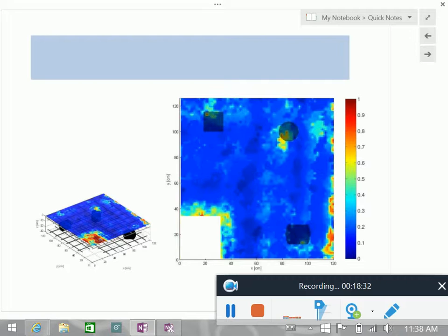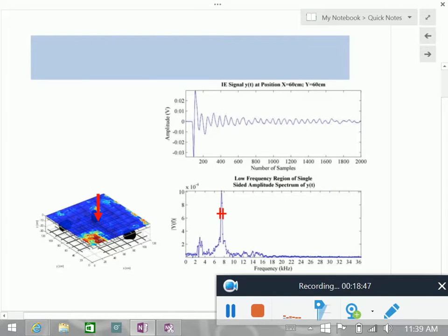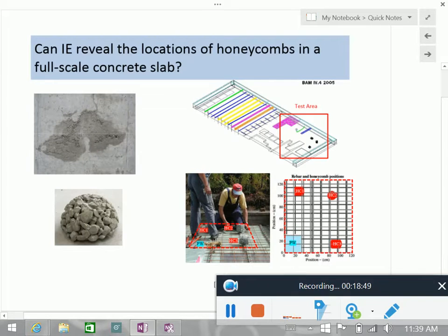So in reality, can you use a hammer to hit the material? We really don't use a hammer in impact echo. Do I have a picture of our impact echo device? No, I can draw it for you. There are different ways. Basically there is a mechanism where you have a small sphere, and let's say there is a magnet that releases it, and then you have an impact. It's a very tiny impact. It's not really a hammer.